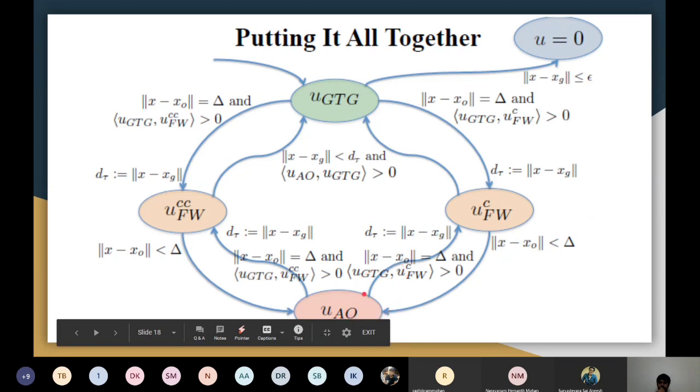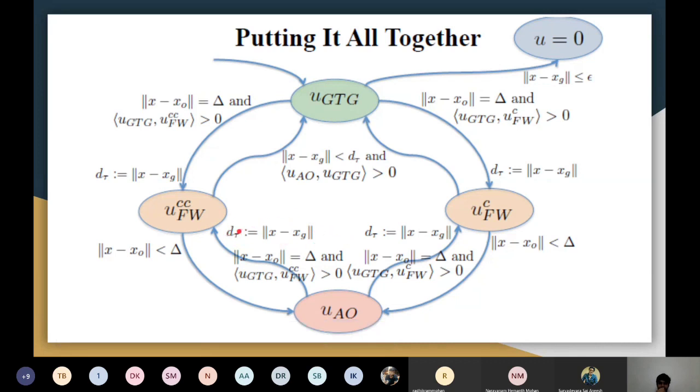So there can be a situation that I'll have to now follow the wall in counterclockwise or clockwise direction. Again, we'll see that by checking this particular condition. And this delta thing is obviously that we have cleared the obstacle and we can start following back my wall. So say this time I went to the counterclockwise direction because of this condition. Now again, you can see I have this as my reset condition. So I'm storing the distance that I'm away from the goal at the point I try to enter this behavior.